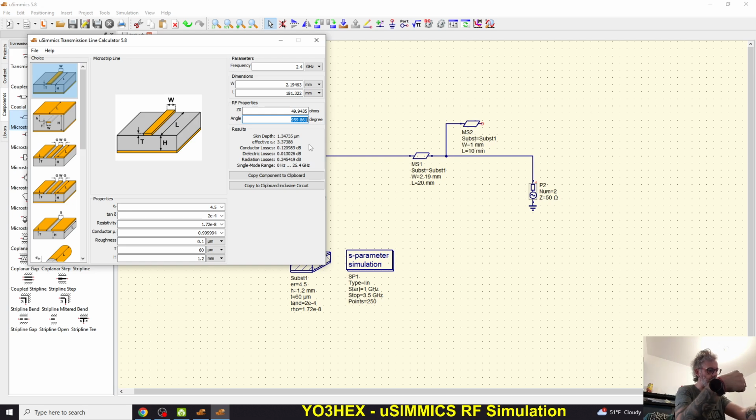So you have 90 degrees first and then you have 90 degrees again, which would give you 180 degrees. So by the time that the signal is going down and back because of the full reflection, it's open, you would get a 180 degree out of phase signal that will cancel out the frequency of interest. Okay, so let's say I would like to have a 90 degree type of phase shift, that would give us a length of 17-ish millimeters.